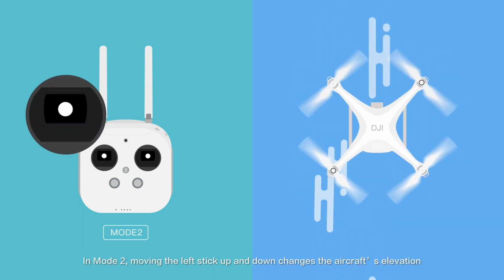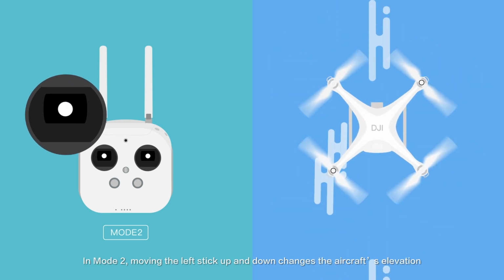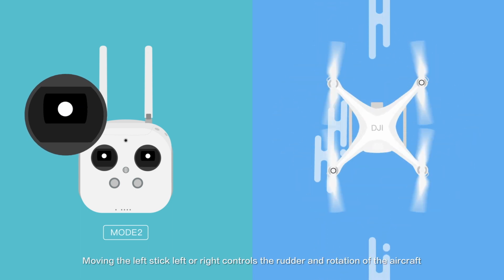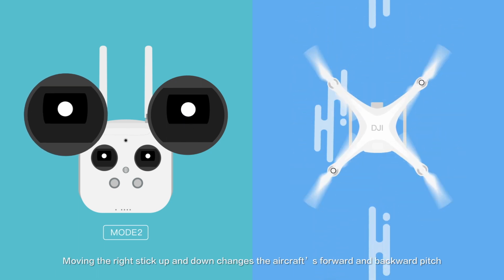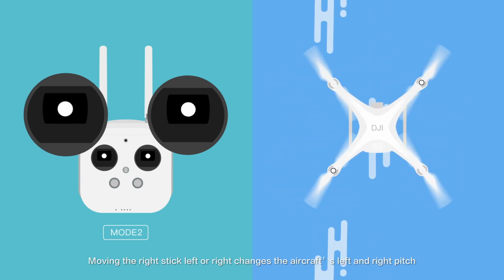In Mode 2, moving the left stick up and down changes the aircraft's elevation. Moving the left stick left or right controls the rudder and rotation of the aircraft. Moving the right stick up and down changes the aircraft's forward and backward pitch. Moving the right stick left or right changes the aircraft's left and right pitch.